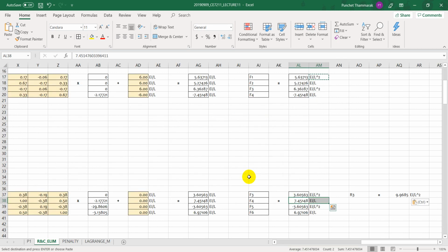Why do we have number 6? We have a hinge, but at the hinge we have the rotational spring attached. So the relative rotation between two members will produce the bending moment across the hinge, right? So that's your spring stiffness, your moment you receive over here.